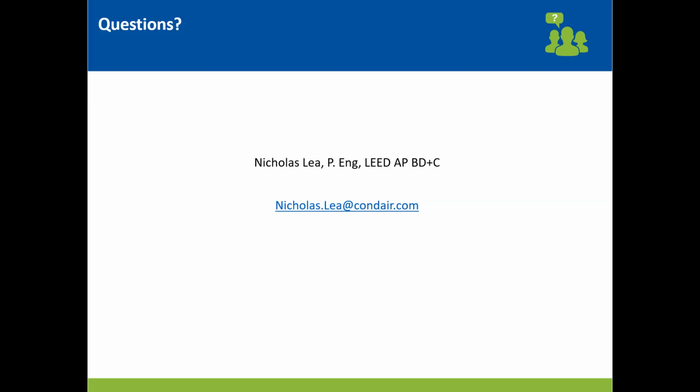Even though that 85% relative humidity is quite humid outdoors, once you bring that air inside the building, as we saw in the earlier example, and heat it up, that 85% is going to drop quite significantly. And you will still have a need for adding moisture to bring us up to that mid-range. Probably not as significant of a need as what you might find in, say, Calgary, where it can be cooler and drier and at a higher elevation as well. But there would still typically be a need.